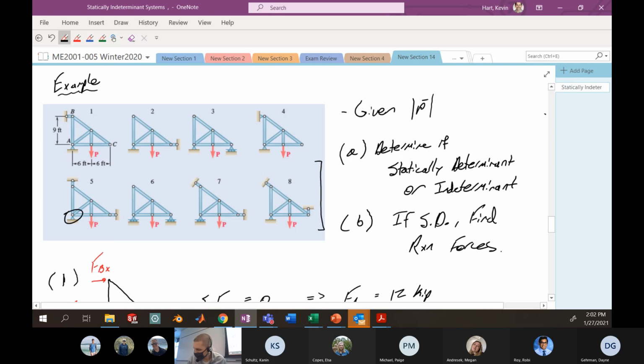This truss arrangement, number 5 here, not to be confused with Mamba number 5. We've got a pin in the lower left, and two bar reaction forces at the top and bottom at B and C. Remember that these bar reactions have a single force in the direction of the link. That's what we were assuming for this problem, and we'll prove this mathematically later in this lecture. Each of these links carries one reaction force along the direction of the link.